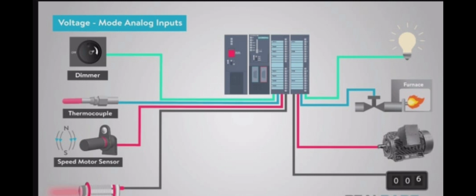As simple as that. The most simple example of analog input is the valve operation. It means the 4 to 20 signal indicates how much the valve is opened. That is 4 to 20. In between those numbers, it will come to know